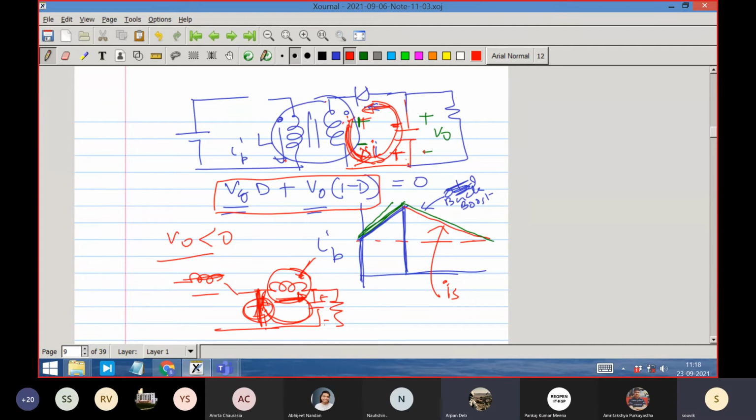It is definitely simpler, but you must understand that it is isolated, but it is not really like a transformer. It is a coupled inductor, because its flux levels are at this high level. In a transformer, we said that the flux levels, if I draw them, are either like this, or maybe like this and like this.